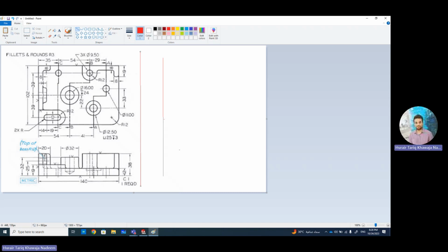It is actually a hole over here. You can bring this line over here, and you will see that this hidden line is actually because of this hole. And this hole is actually all through. So why not make this whole feature in the sketch, and make it extrude all through. But we can do it afterwards as well. So let's forget about the hole because we have to cut it on the bottom side as well. So we can do it afterwards.